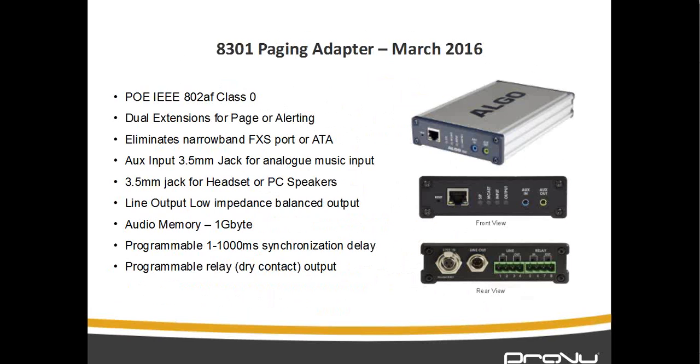Obviously, because it's IP, as I explained before, there will be a delay. It allows you to create a synchronization across the board, so audio comes out at the same time. It is PoE, so you provide power using PoE. They do have other line outs and relay inputs and relay outputs, which can be integrated with an existing amplifier system or a PA system, and obviously it allows them to convert it into SIP or IP.